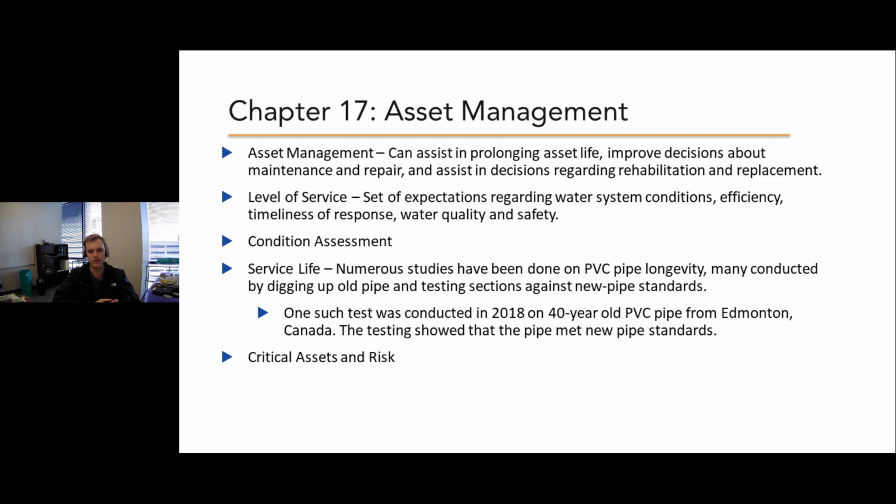There was one done in 2018 as part of a series being done by EPCOR. That's Edmonton Public Utilities. The 2018 study was done on one of the first PVC pipes installed in Edmonton. It was about 40 years old, and it was done by Doug Sargent. He published that in a number of conferences, AWWA and ASCE conferences. And it showed that the pipe tested to new pipe standards. They tested that old pipe to present standards used for new pipe production and found that there was no issue. It tested as if it was new.